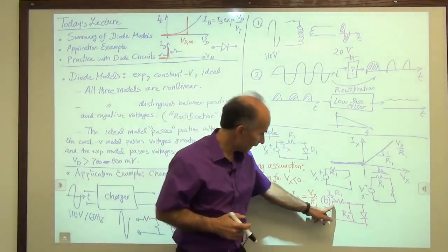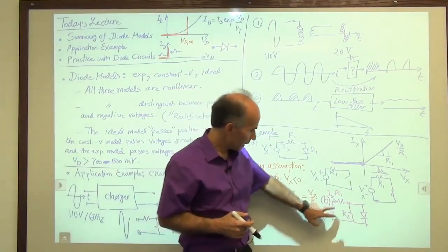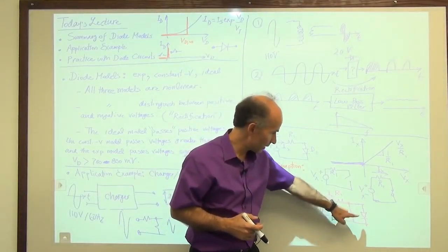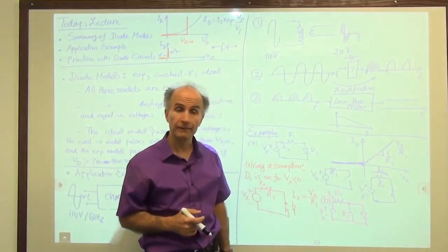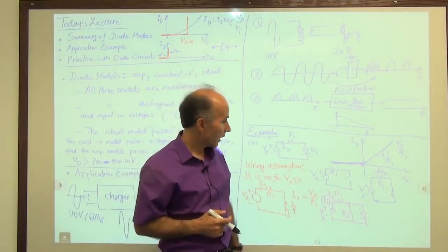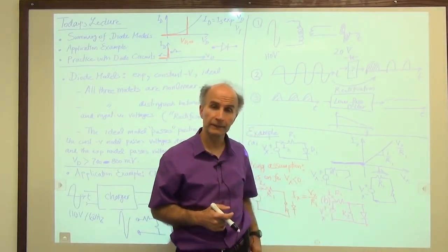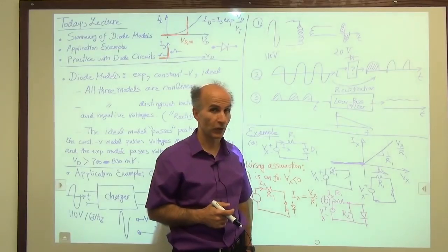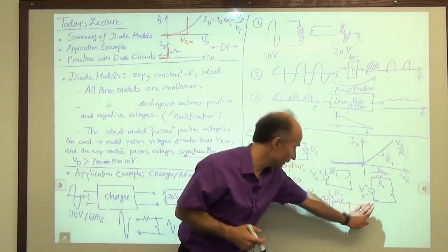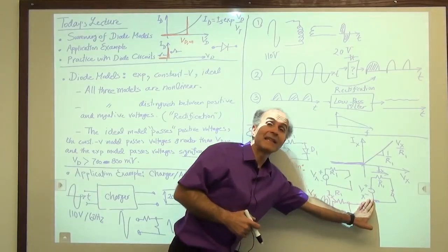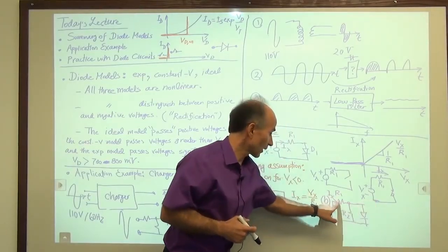All right, so if Vx is very negative, what do we expect? Well, again, we expect that this voltage would be probably negative with respect to here, which means this diode will be off. If the diode is off, how much current do we have in Ix? Well, it's not 0 anymore, right? Because if the diode is off, the voltage source Vx is connected to the series combination of R1 and R2.